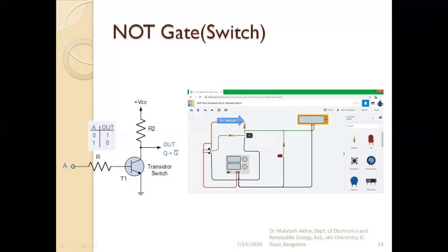When the switch is slid down, the middle point, which is A, is equivalent to connecting to this. That is, this is connected to the negative terminal of the power supply, which is the ground. At the same time, this emitter is connected to the ground. The emitter is connected to the 0 volts or the negative terminal of the power supply.